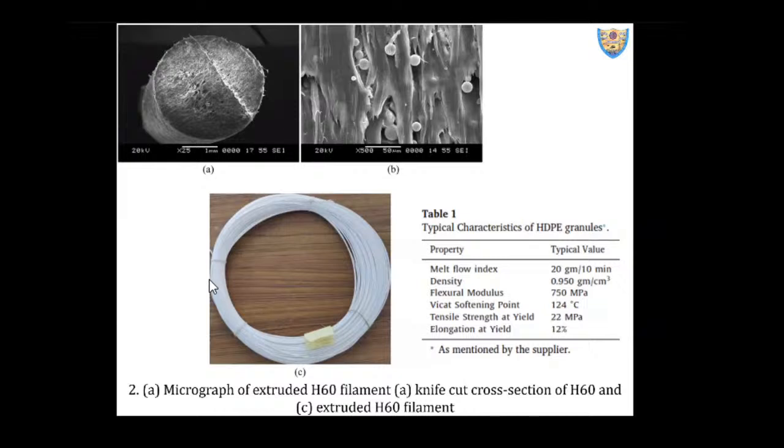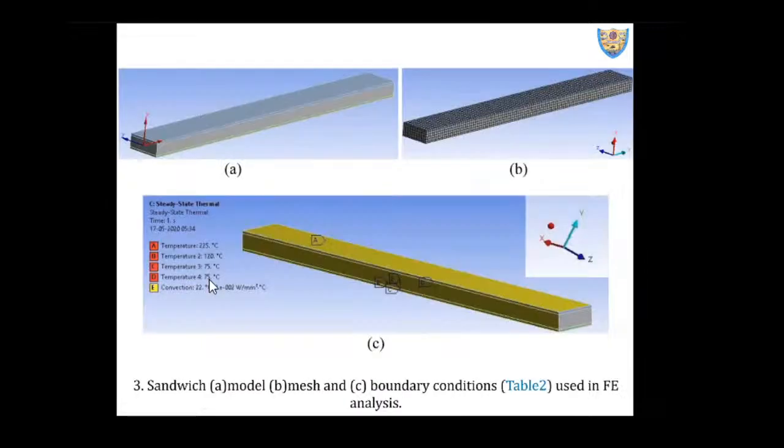Then we thought of printing the sandwich all at once. Because all of us know that when I say sandwich, the core, the central part, is manufactured differently, and you have the slabs available. Then conventionally what you do, you take the jute skin or whichever skin you want, glass skin, dip it in the epoxy, put it in the mold. So you prepare a bottom skin, then place the core on top of that, and then on top of the core, you again prepare the top skin by dipping it into the epoxy resin or compatible resins for that matter, which you want to use, and then put it on the top, close the mold from the top, and allow it to settle. If you are using Lapox L12 epoxy resin, I think we generally go for 24 hours of clamping it and giving it time to settle. After 24 hours, you remove it. Then what you have here is a sandwich.